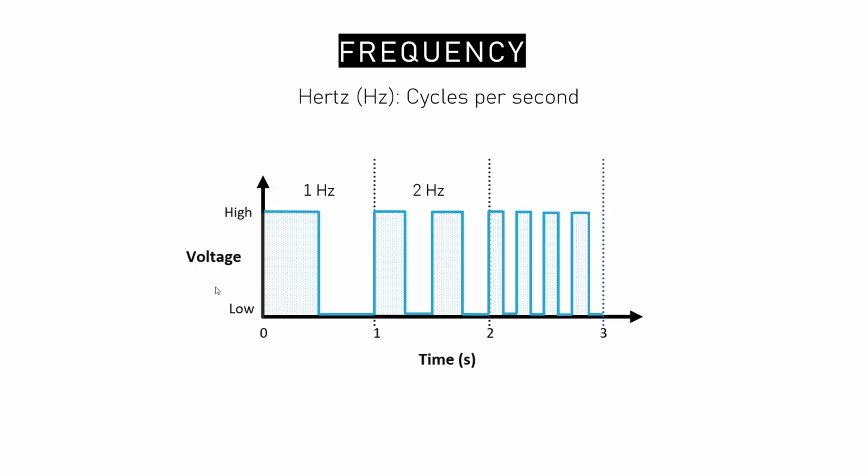In something like motor control, including DC motors or 3-phase AC motors, a common PWM frequency range is usually from a few hundred hertz to several kilohertz. For motors, higher PWM frequencies generally offer smoother control and quieter operation, but may result in higher switching losses. Whereas for LED dimming, PWM frequencies are often in the kilohertz range, typically above 1 kilohertz.